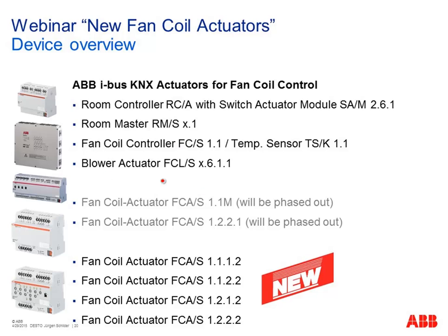And the blower actuator, relatively new. It's called blower actuator because it's mainly used only for running the fan at different speeds, but as there's an additional output, you can also connect an electrothermal valve drive. But be careful, only completely open or close, so we cannot modulate, we cannot position the valve. It's a, let me say, reduced solution for fan coil control, but in principle possible for some simple applications. And what do we phase out very soon?